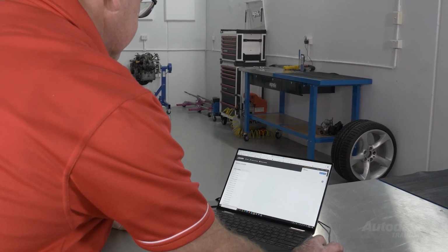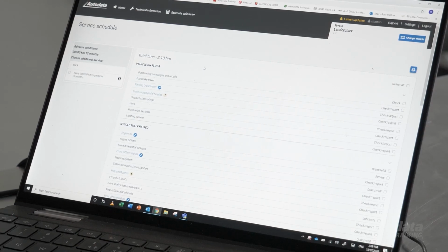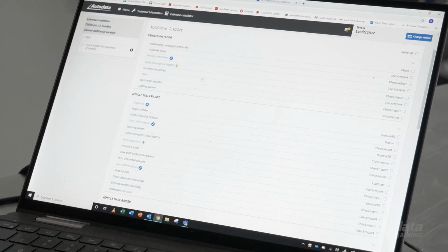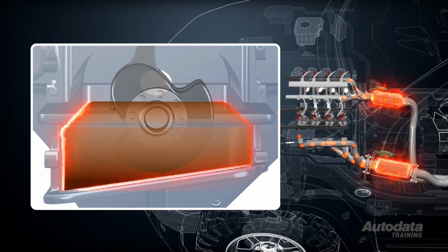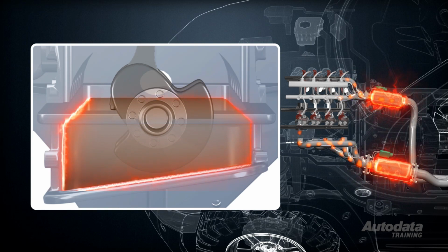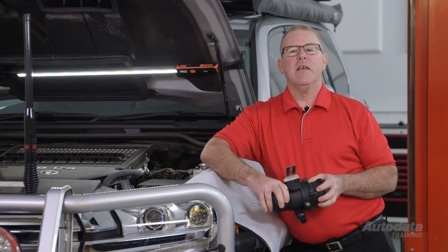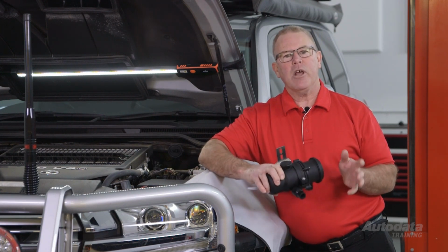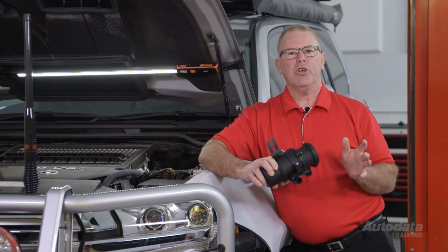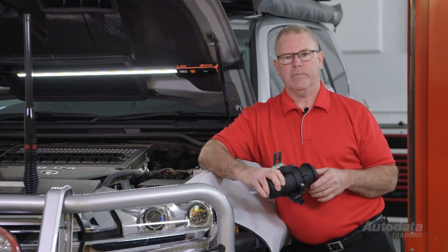Adhere to service schedules and check the oil level regularly. Remember, you may have to have more frequent oil changes depending on driving conditions. This is especially relevant for vehicles that use dosing, as it's not uncommon for the oil level to increase significantly due to oil dilution. Some vehicles may benefit by fitting a catch can. This will not only help your DPF, but it'll also keep your intake much cleaner too.